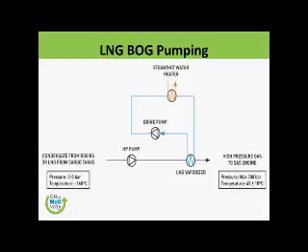So of course LNG is a big money investment, but even the companies making a new ship, say container or bulk carrier, are making it as LNG ready ships. Means there is a space, and the piping arrangement or design is already there. The only thing is, whenever it is the right time, they will put it in there.